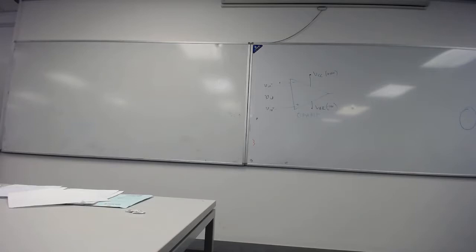Would it be a short? No, it's not short. Short means zero voltage, and you are not getting zero. Should I give you more chance, or should I just pronounce it myself? It's a comparator. Between two inputs, it's a comparator. It compares two inputs, whether this is larger or this is larger, that's all it's doing. So when you have an amplifier with very high gain, it works more like a comparator rather than an amplifier.